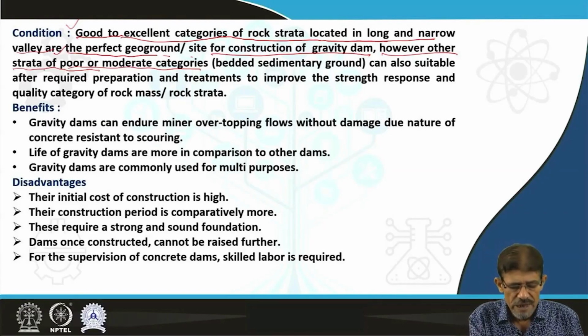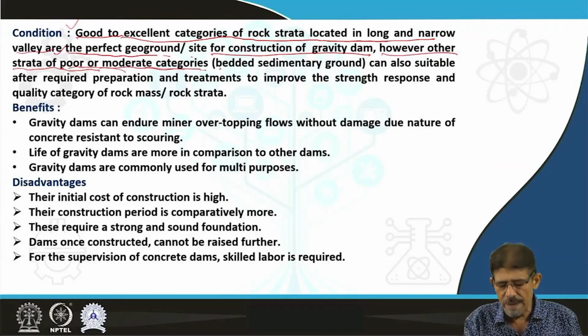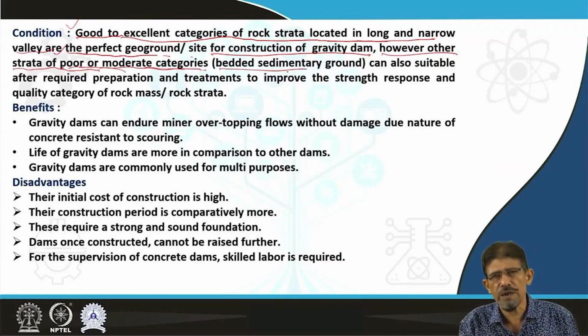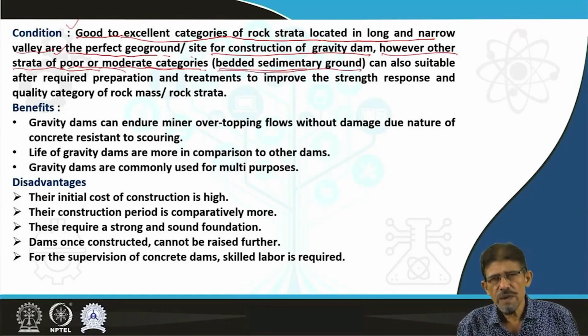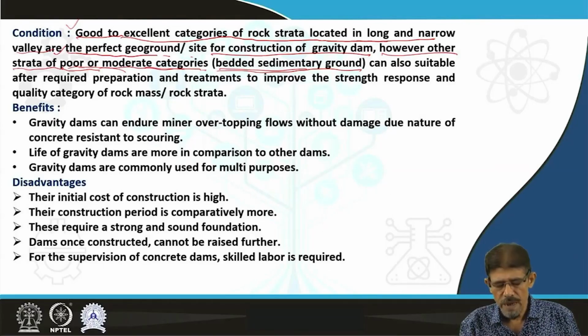So in case of strata of poor and moderate category like bedded ground, we have already discussed different types of bedded ground, layered ground, heterogeneous bedded ground, etc. Bedded sedimentary ground requires some proper preparation and a high level of treatment before placing the gravity structure like a gravity dam.